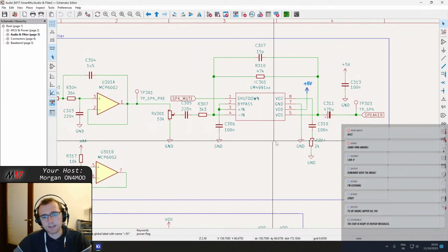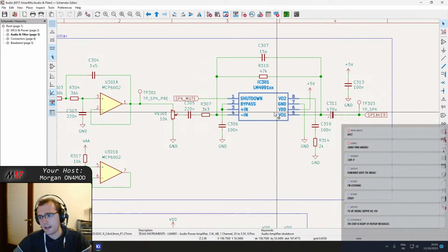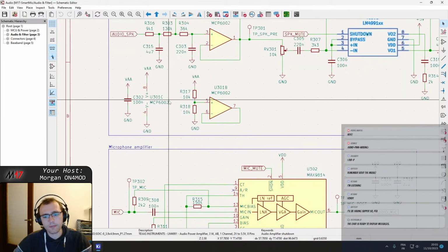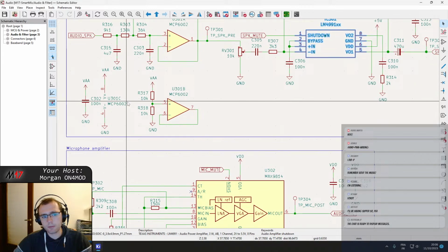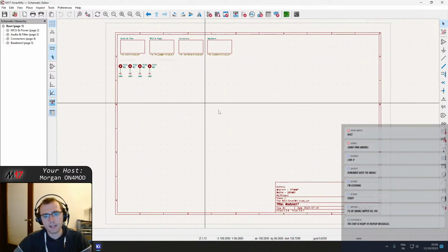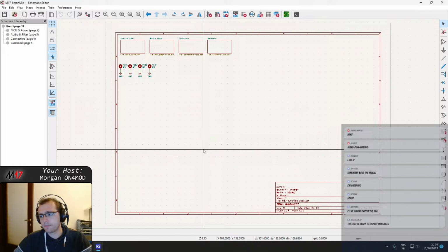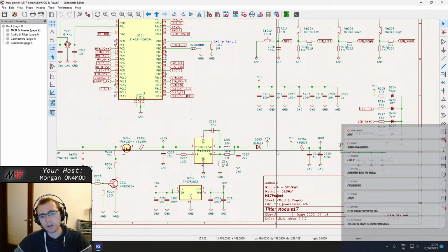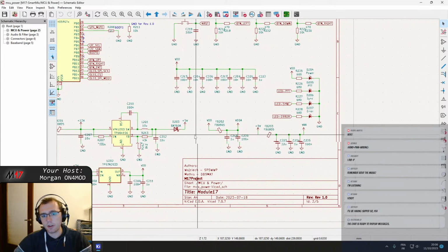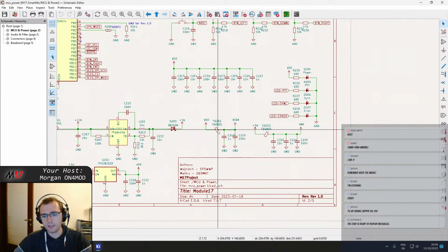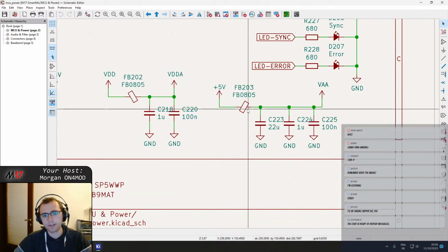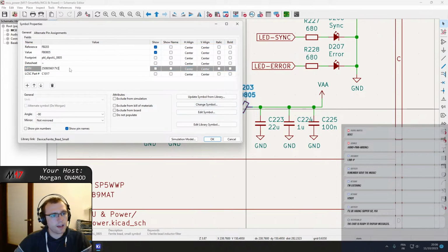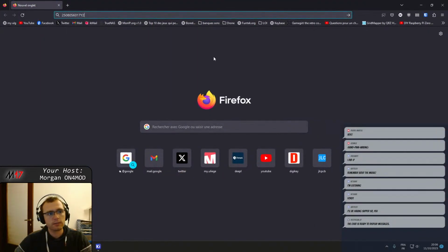The problem is that this one is going to have some switching noise on it, which I don't like, and maybe mostly the problem with VAA is that a ferrite bead is not enough to filter this switching noise. Switching noise is at 800 kilohertz, but if you have a look at ferrite beads, usually they work at much higher frequencies. So I think we have a manufacturer part number, so let's have a look at this one to show you what I mean.